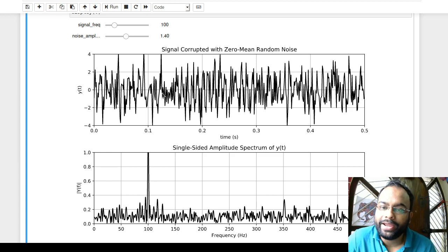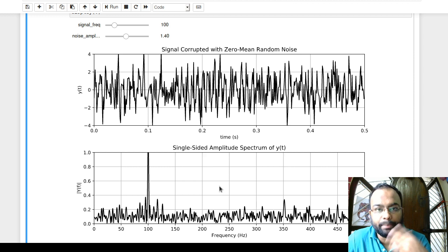So we do live in the time domain. As time passes for the signal, this is the behavior of the signal. That is how the signal fluctuates. But if we calculate the Fourier transform of the signal, in the frequency domain we actually get to see the internal components present in the signal. That is what we get to see.